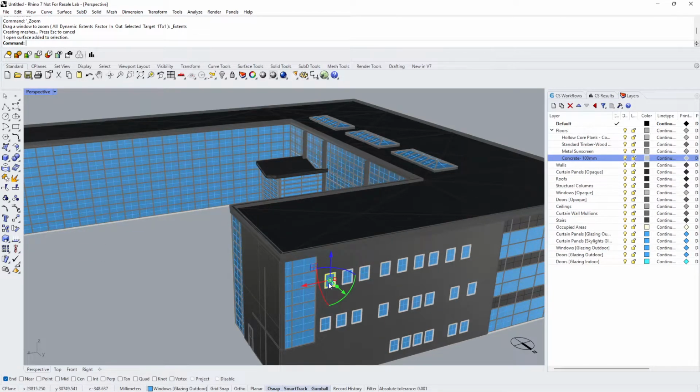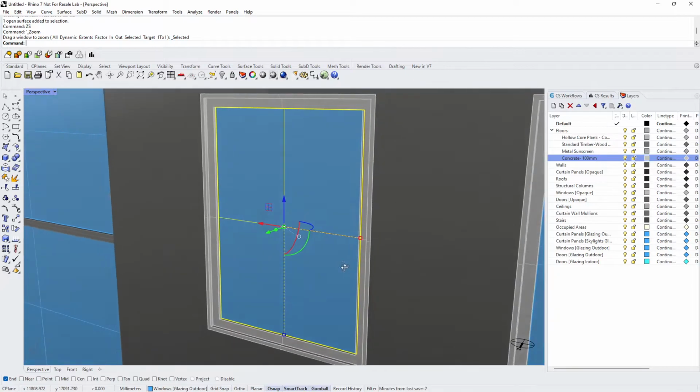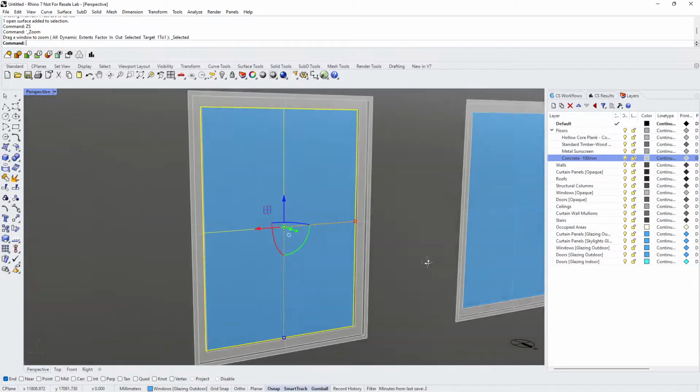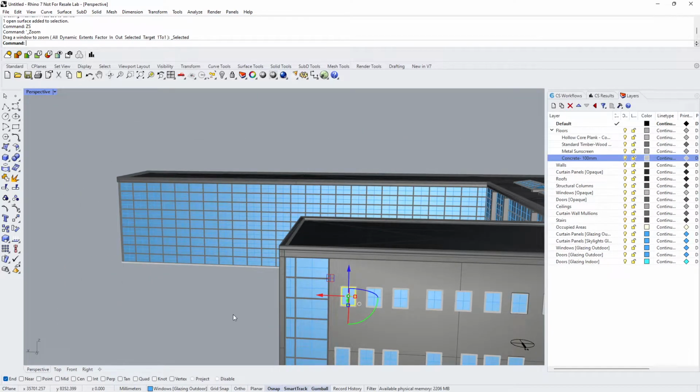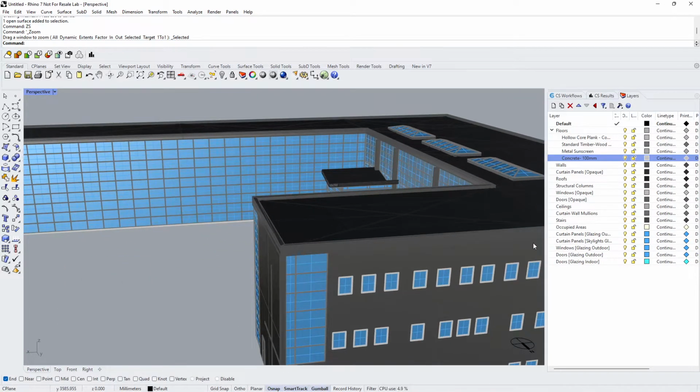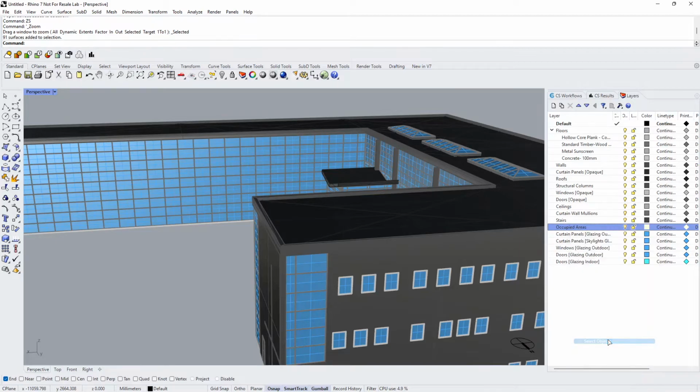Looking at some of our windows, it's clear that the import process automatically converted the Revit glazing solids into single surfaces, which ensures correct behavior in the Radiance lighting engine. Double-check that all occupied areas have surface normals pointing up.